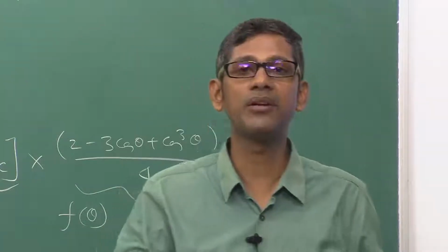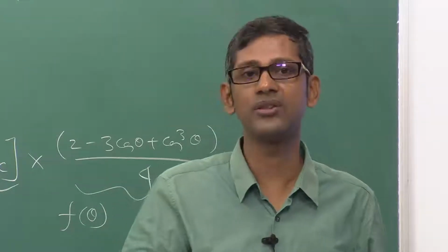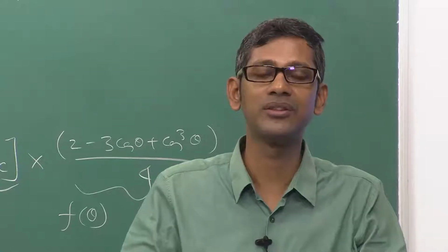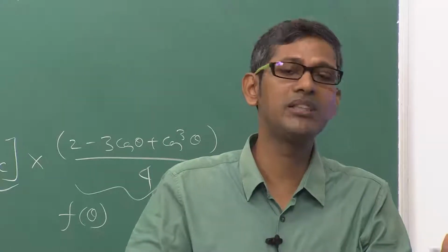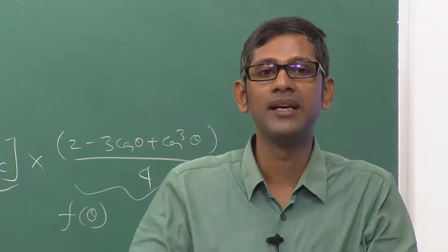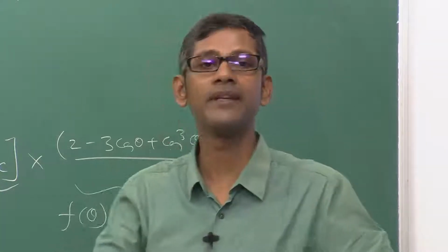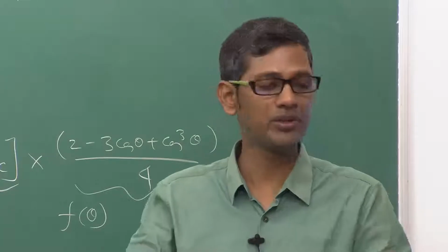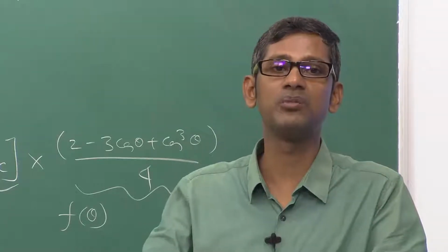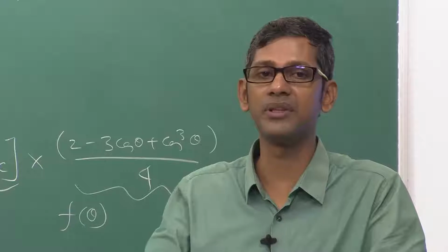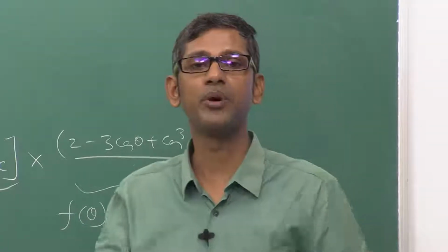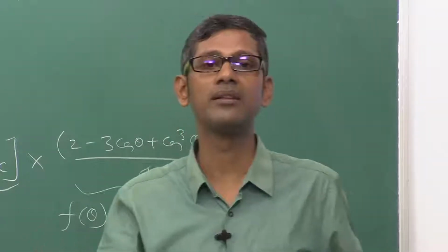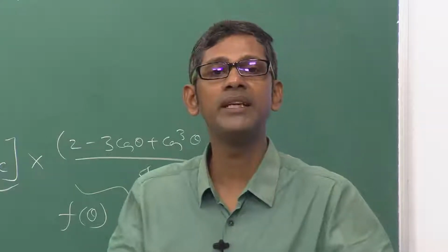When nucleating graphite on graphite, theta will be very small, because graphite will have a perfect match with the crystal forming from the liquid. So theta will be very low, f(theta) close to 1 actually in those cases. A little distortion in the surface is possible because of the temperature differences between the solid graphite and the graphite forming on the graphite particles. And the barrier is very small.